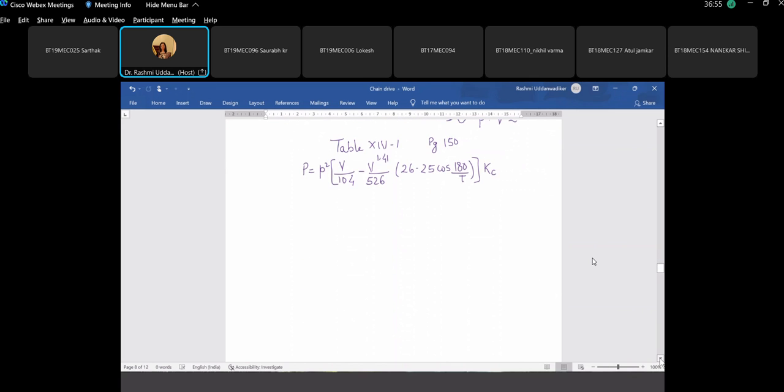Please take the problem statement. A 1000 RPM motor is used to transmit 7.5 horsepower to a compressor shaft. Power is given in horsepower, and the design data book is also giving you power in HP. So we'll keep it as it is for now. Later we'll change it to kilowatt. So I repeat, a 1000 RPM motor is used to transmit 7.5 horsepower to a compressor shaft which is running at 350 RPM.